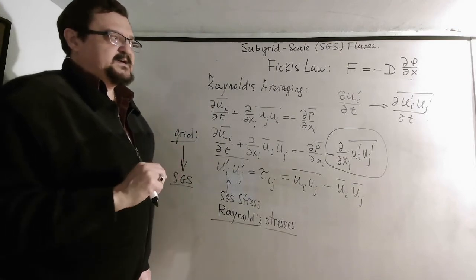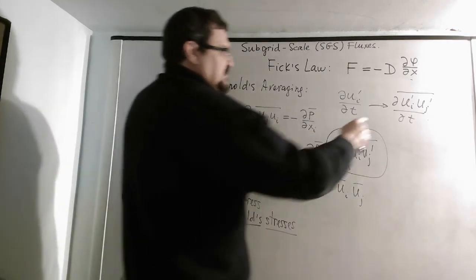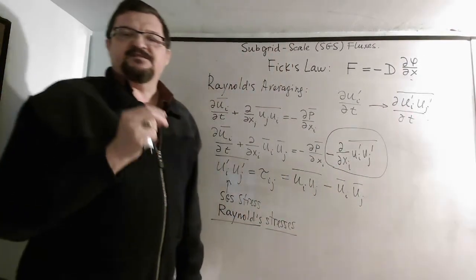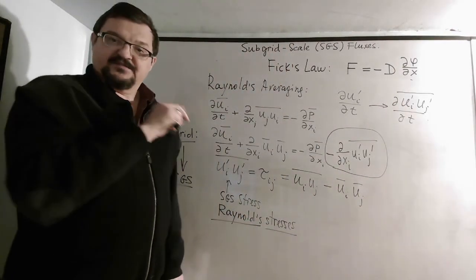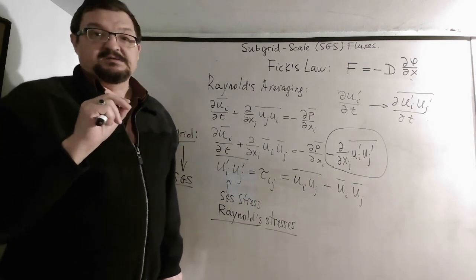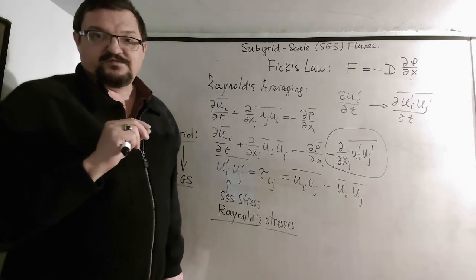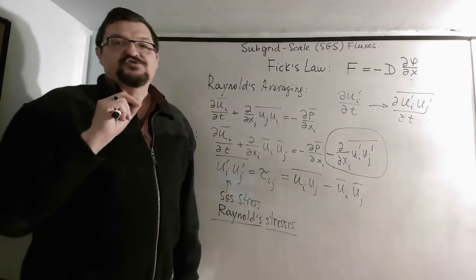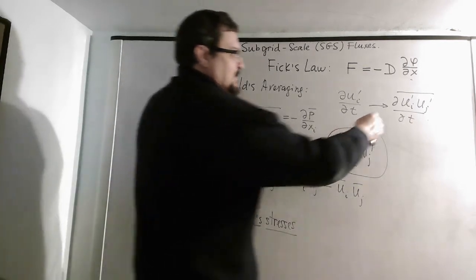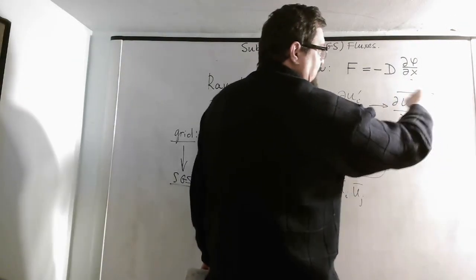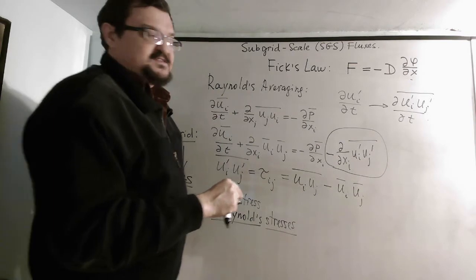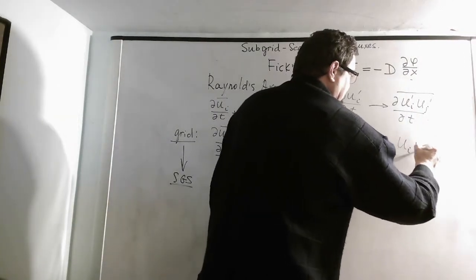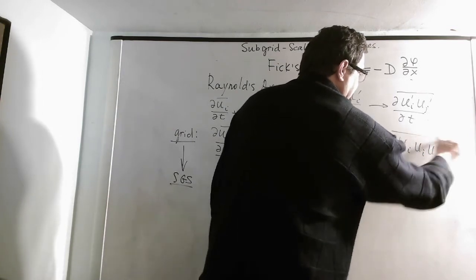The problem is that these equations for the Reynolds stresses will have not only Reynolds stresses on the right hand side, or binary products of these velocity components like here, but also triple products. So the second moment, in this case the stress, actually depends on the third moment, terms like u_i u_i u_j.